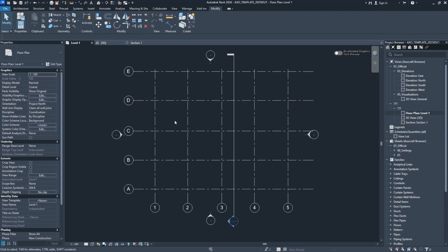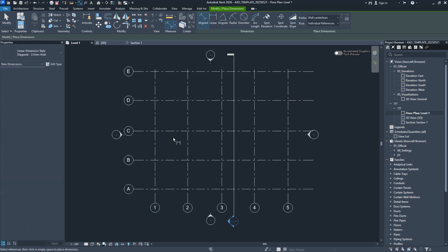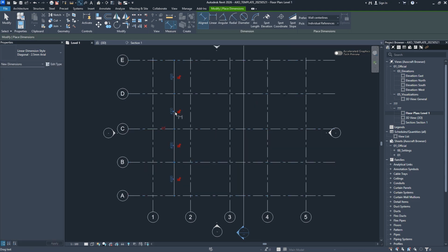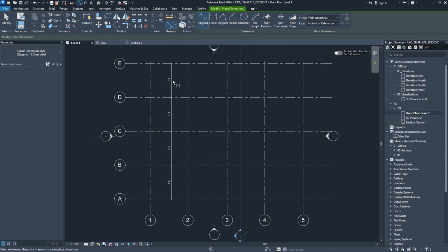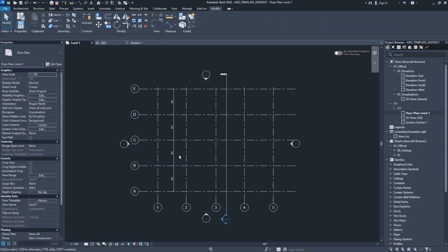And if you ever want to make sure that they are perfectly aligned between each other, what I would usually recommend is to click here on measurements and then just select 1, 2, 3, 4, 5. And as you can see, even though they have different measurements here, if you just click the equality icon here, then they will all be aligned accordingly.